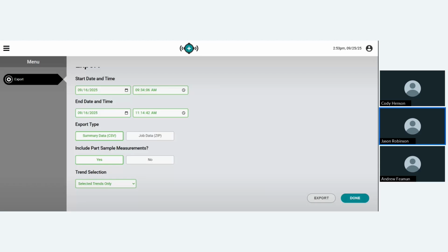How do I set up a warning then? Well, a warning would be like, let's say hold time, and your upper and lower limit for hold time is, the lower limit's 4 seconds and the high limit's 6 or 7 seconds. If you violate those, it'll throw the part away. A warning would be something tighter than that, to where if someone changes it, it's not 100% bad, but it might be.